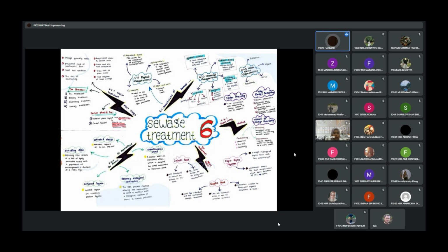It is based on sewage quantity needs, projected needs of wastewater flow, local soil condition, the cost of constructing, requirements under the service area, sewers, and site local environment, space and land the plant needs, and final disposal of treated sewage. And then the process has four stages, which are pre-treatment, primary treatment, secondary treatment, tertiary treatment. And the third should be treatment plant layout and canal and vessel.